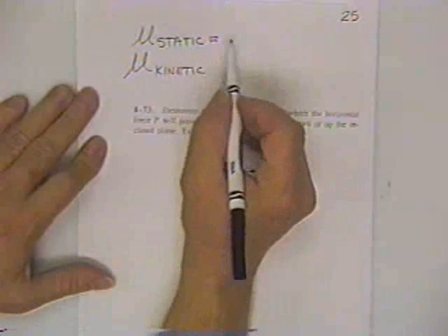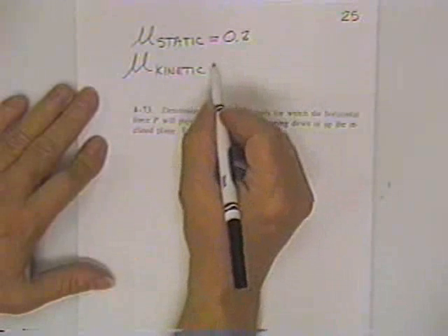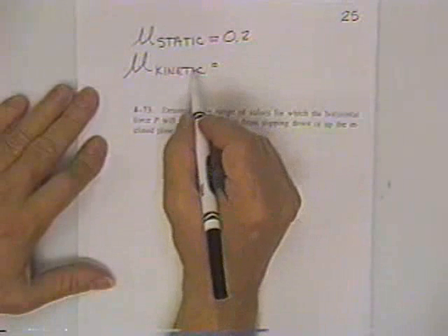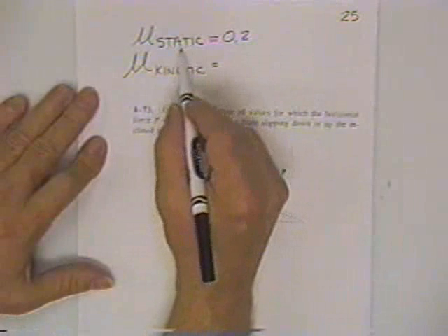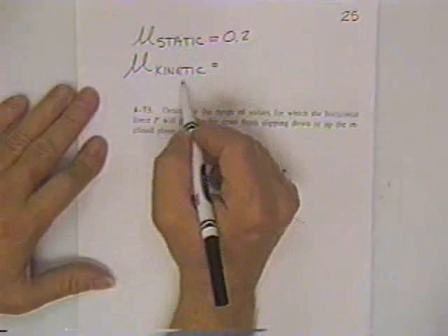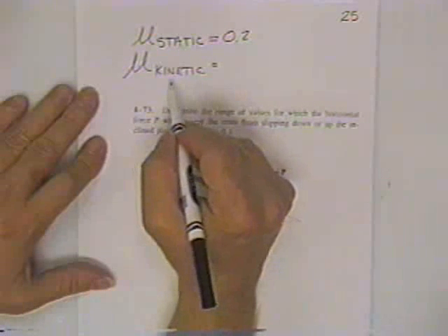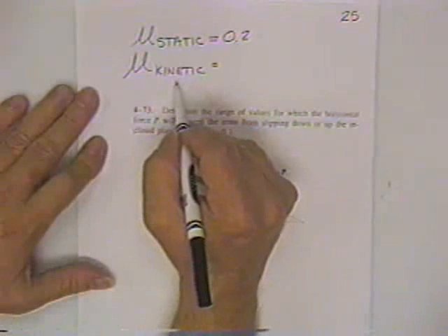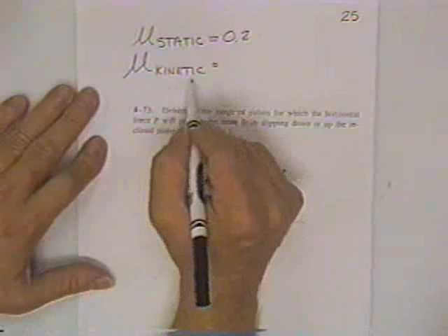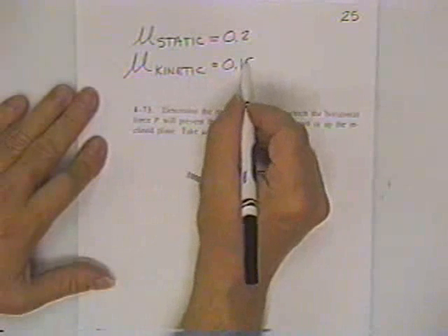The static coefficient of friction is generally larger, might be 0.2. That is the coefficient of friction it takes to break it loose. Once you get it moving, the little raised spots and indentations and imperfections that used to be locked together are pretty much dynamically rattling across each other, and so this number drops.